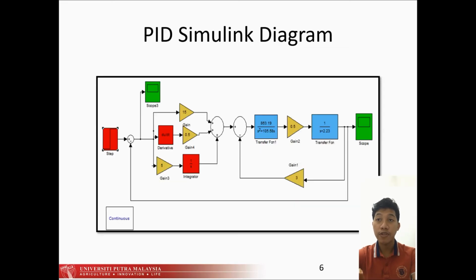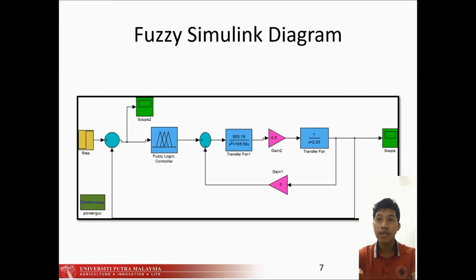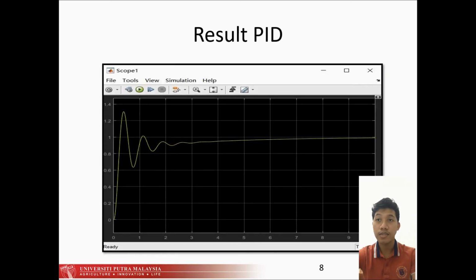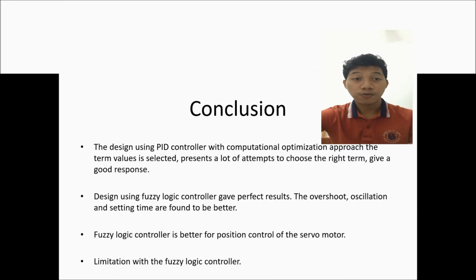So here is the PID simulation diagram, and here is the fuzzy simulation diagram, and this is the result. And for the conclusion, we found out the fuzzy logic controller is better for position control of the servo motor, as it is better in the overshoot, oscillation, and settling time.